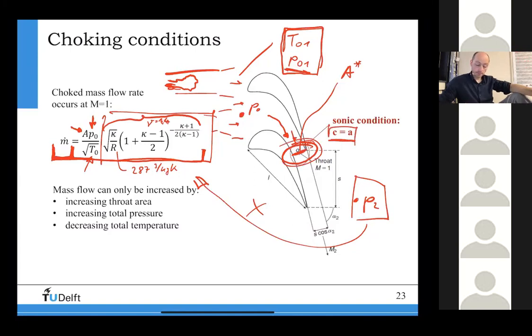Okay? And so the choked area means basically that the flow velocity is the same as the speed of sound. And the speed of sound can be defined by also simple thermodynamic relations. You just need the mass conservation equation and the energy conservation equation. And then the speed of sound usually is defined as the partial derivative of pressure with respect to density, but we know that pressure, density, and all these other parameters always depend on two thermodynamic properties for a simple substance, which means we need to define here this partial derivative in terms of keeping something else constant, right?